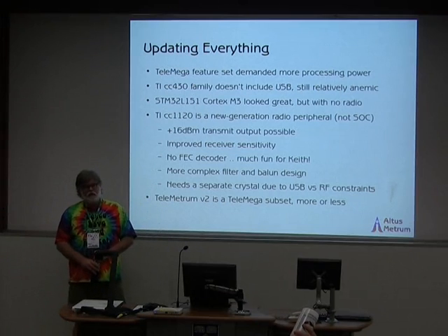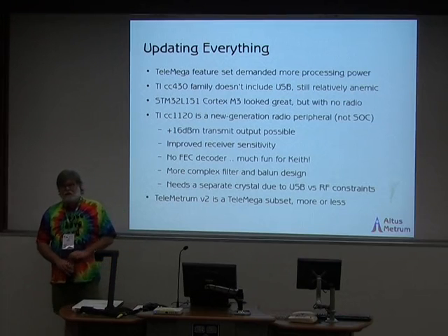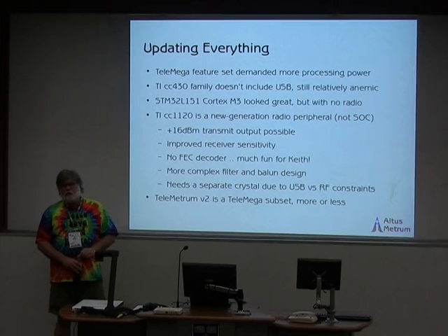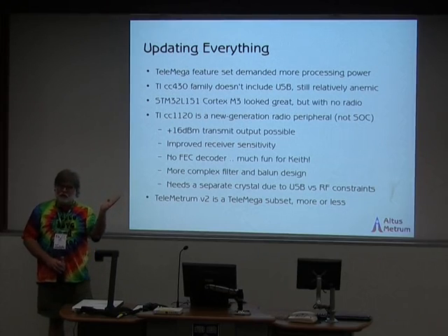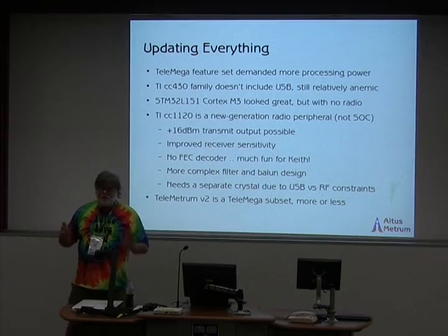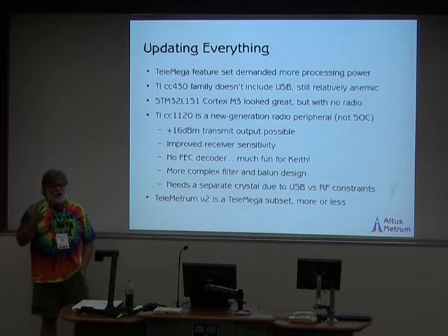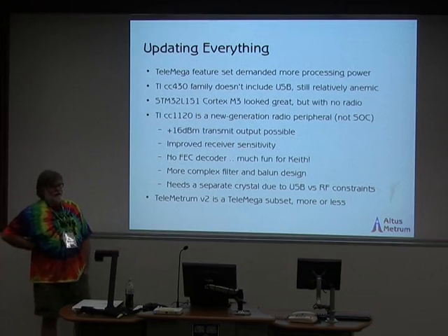So actually, a guy in the US came up with an interesting idea. He spent quite a bit of time analyzing sensors. It's all written up in Rockets magazine over the course of several issues. In the end, he basically did an inertial measurement unit design to figure out which way the rocket's oriented. Is it still going mostly vertical, or has it laid over for some reason? What he designed was a board that could go between your flight computer and the pyro charges to provide an extra degree of gating on whether to fire the charge or not. So it basically provided a pyro event inhibit if you were too far away from vertical. And it was called the Tiltometer.